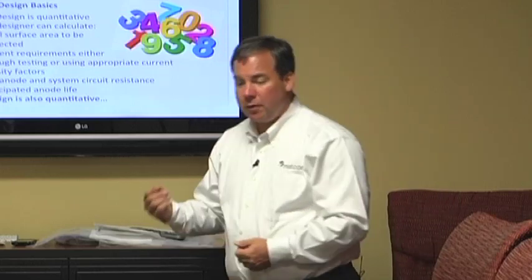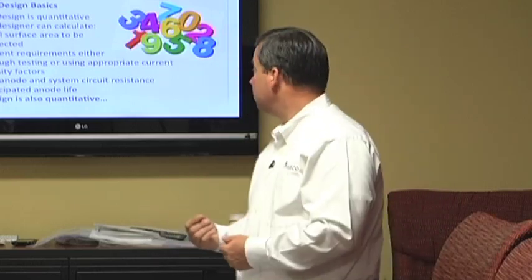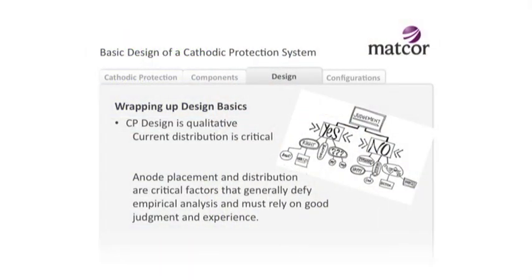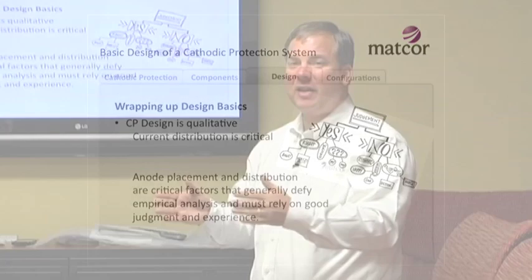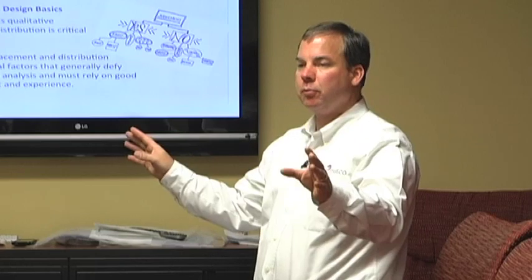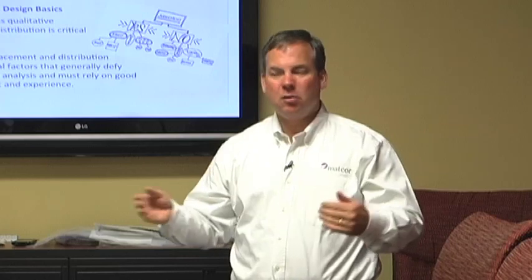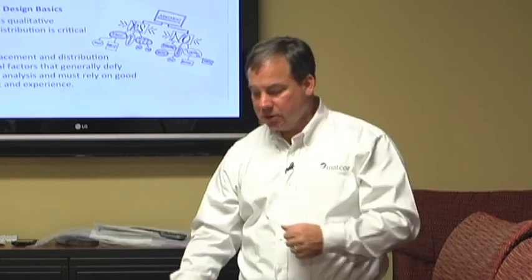However, the design is also very qualitative. Okay? Why I say CP design is qualitative is because it's one thing to calculate how much light I need to light up the structure for as long as I want to light it up. But there's also the issue of where do I put the lights? Where do I put these anodes to make sure that current's distributing properly to the whole structure? Okay? And that's a qualitative assessment. It's really almost impossible to completely calculate that for every unique application. Some applications it's easier than others, but in many cases it's a pretty complex consideration.